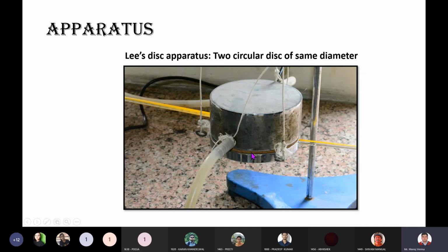This cardboard is actually the specimen, the sample of which we are trying to find the value of thermal conductivity, inserted between these two slabs. Okay, so yes, after gaining heat energy from this steam, this slab A will act as a heat source, and this heat energy will travel towards slab B through the mode of conduction, through this cardboard sheet, through this bad conductor.